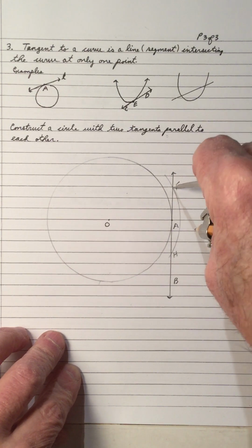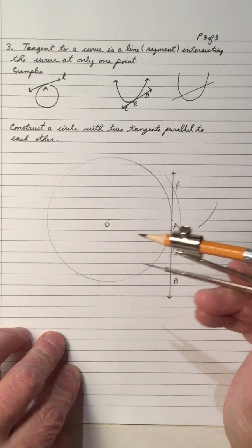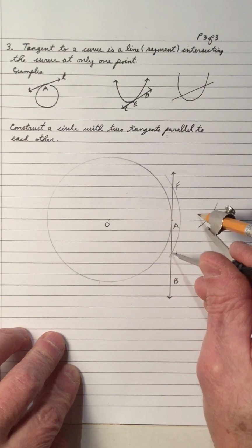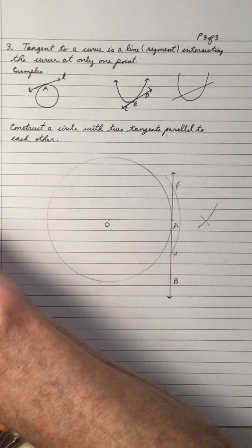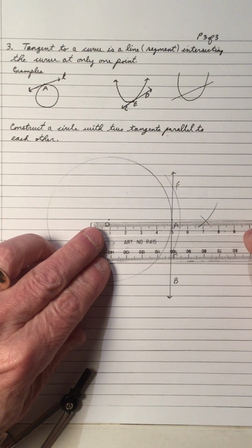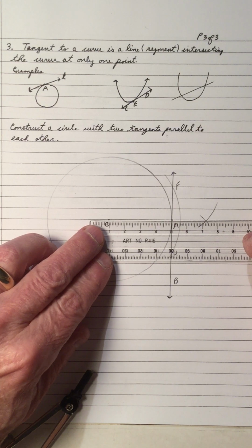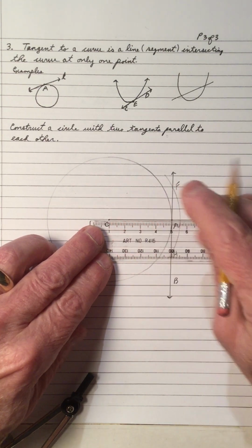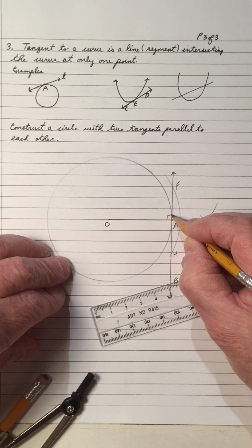And we did this before in a previous video, so we make an arc. Now we'll put it at H and make another arc, cutting the previous one. There it is. So what I've done now is that from O to that arc is perpendicular to the line. So I drew a perpendicular from O to this line. And so here it is, perpendicular.